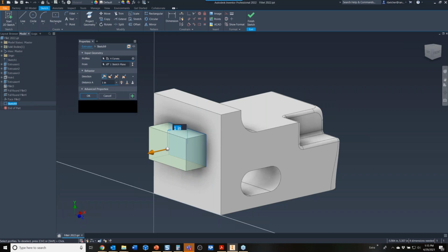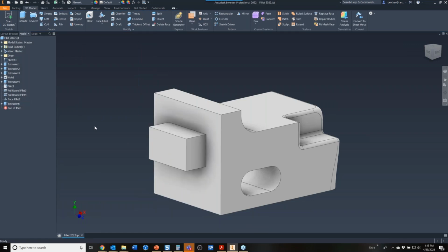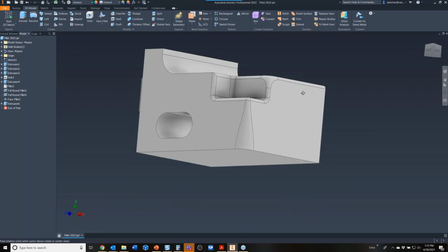If you want a surface, you simply activate the surface option, you'll get a surface. If you don't want a surface, you'll deactivate the surface option and get a solid. So these are little improvements in the properties panel, but I think it helps, it removes a lot of clutter on the panels, makes them a little more user-friendly, a little easier to understand as you're using the tool.